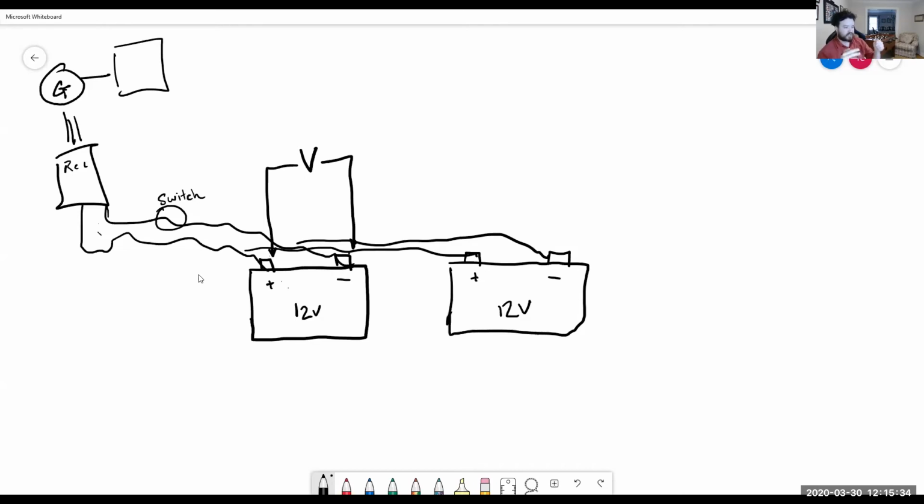If you take the switch, click it off, open up the switch, and put your voltmeter on right away, you will get a higher than normal reading, because you barely gave it any time, so you're not reading the actual battery, but what it was getting charged to. So you just let it sit for maybe 5, 7, 10, 15 minutes, nothing longer than 15.